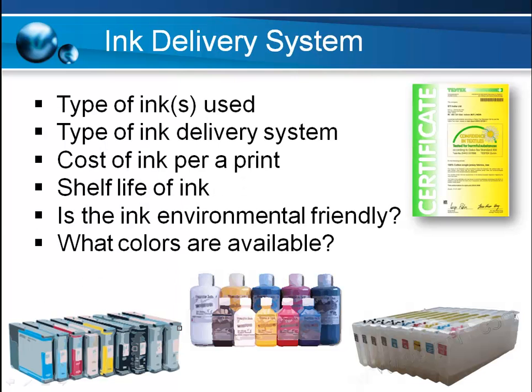Another key part to purchasing a DTG printer is looking at the ink delivery system. Understanding what types of inks are being used, most of which nowadays are water-based inks, but also who manufactures that ink, where the ink is coming from, so that you have a readily available source for that ink, and what type of delivery system is being used.